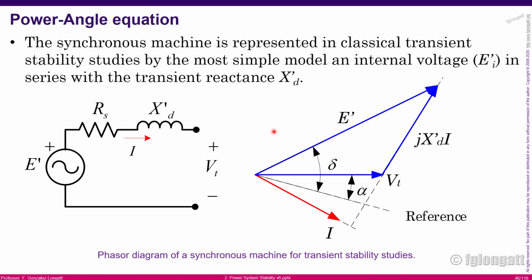All of you must remember that if we are interested in transient stability, right now we need to use the transient model for the synchronous machine. During my classes of short circuit analysis, I introduced three different simplified models for the synchronous machine. What I'm trying to say is there are at least three models: subtransient, transient, and steady state. In this case, I am presenting over here the steady state model, but representing the subtransient behavior, okay?